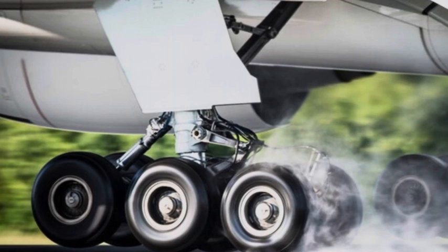And regarding performance calculation, when the weight is distributed amongst more wheels, we can have a better range of the center of gravity, or CG, of the aircraft. So we can have, for example, 4 wheels or 6 wheels attached in the main landing gears. In most large aircraft, there is also a landing gear in the middle of the fuselage. This is because we need more wheels and more landing gears to support the weight of the aircraft.